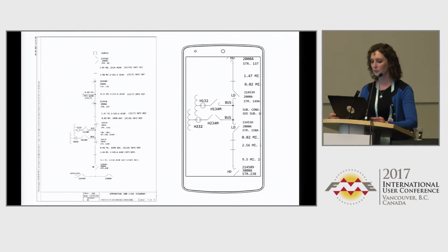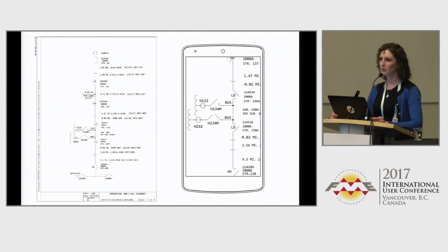All right, so the first one, I did try creating my own font. One of the big problems we have is that FME cannot read MicroStation fonts. For the fonts these DGNs originally use, I probably spent a week trying everything I could think of to get FME to read them and create something similar, and we just couldn't get it working. So we settled on fonts that were similar to each type. Luckily, there were only about 4 different types of fonts being used. If it was font type 4, I set that to Times New Roman. If it was font type 5, I set that to Calibri, etc.